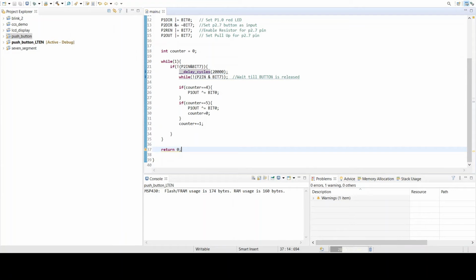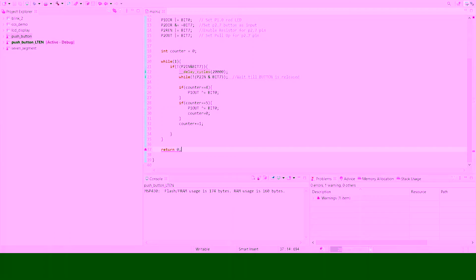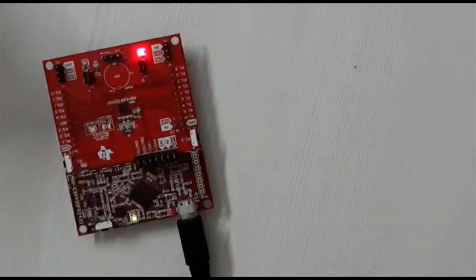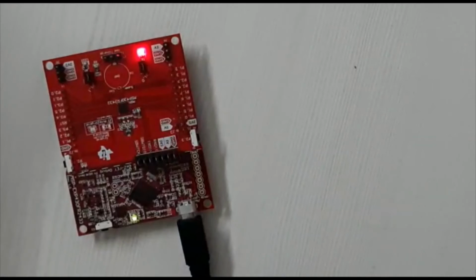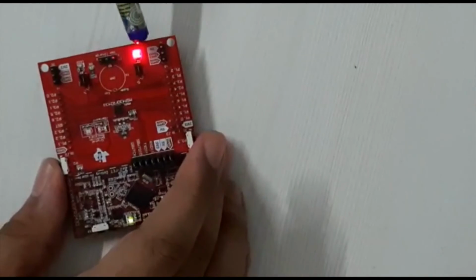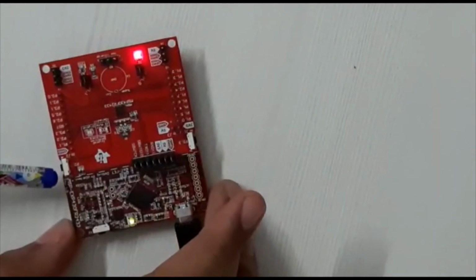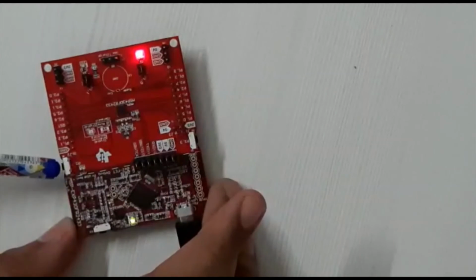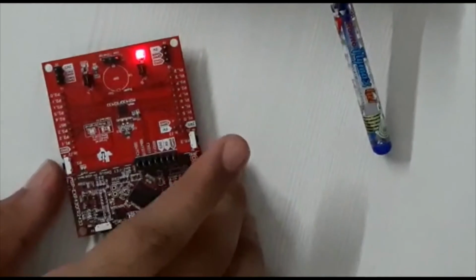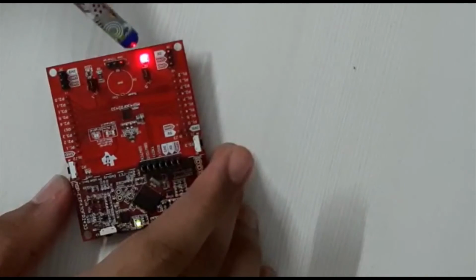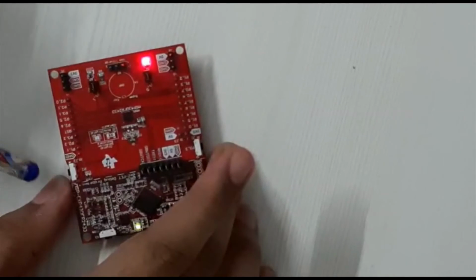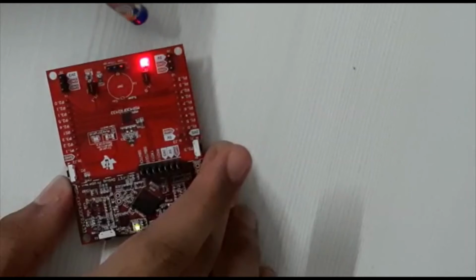in terms of logic. Now let's check whether this is actually working using the microcontroller. So let's continue with our MSP430 demo. The first thing that we need to notice is what our input is and what our output is. Here we had set this particular LED as our output, and this switch P2.7 is going to be our input. So every fifth time this button is pressed, the LED is going to turn on, and every sixth time it's going to turn off. Currently the LED is in its default state, on.